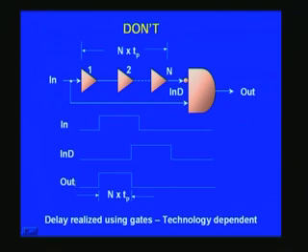This output here is nothing but the same input after a delay. This delay is governed by the total number of buffers that you have, and that total delay appears at the output also. So if you combine these two in this fashion, with note of the bubble here, the outcome is a single pulse, the duration of which is governed by this n times Tp.